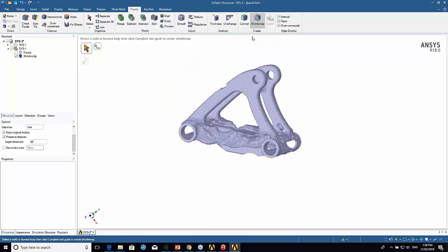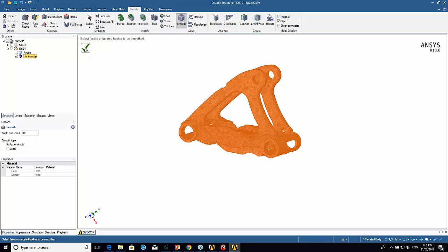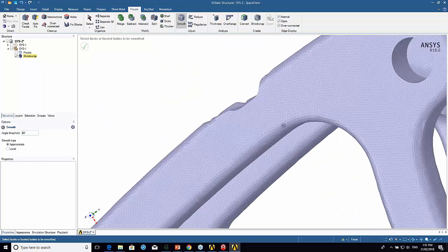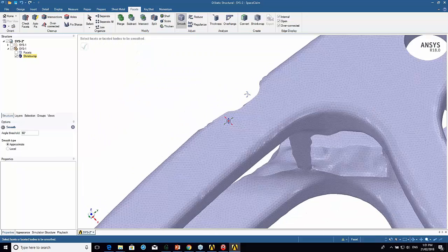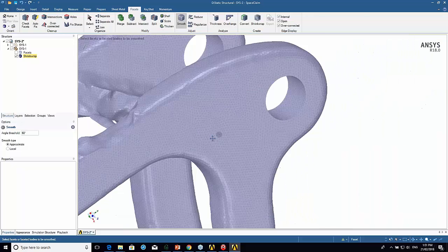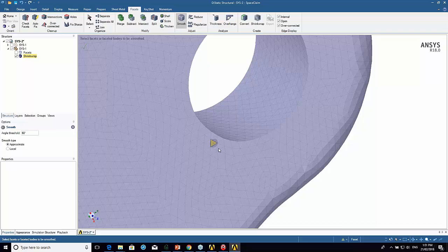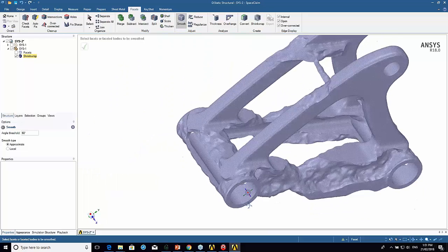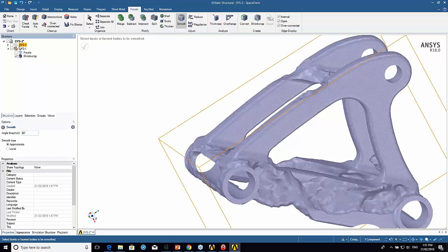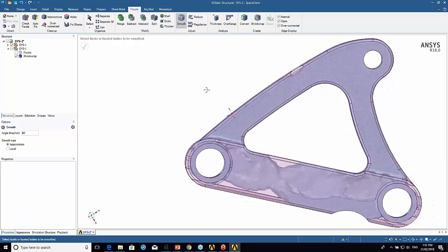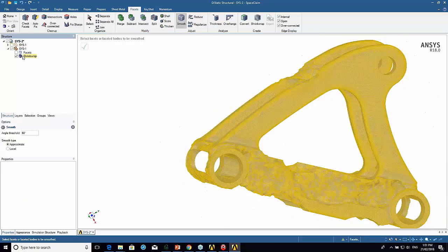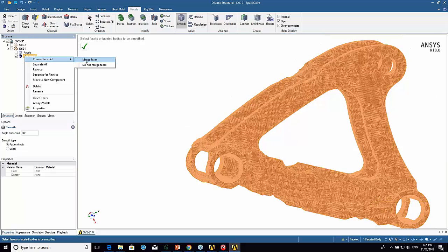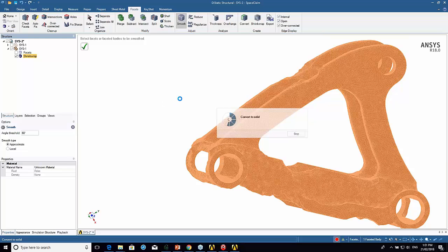alright, so now we can attempt to smooth. So if I triple click, it selects everything. So you can see when it's smoothed, it basically creates a smoother geometry. So you can see I've still got the sharp edge around there, which is what I want. Okay, so you can sort of compare the old to the new. So now I'm going to basically convert this to a solid, which I can basically reuse or reanalyze.